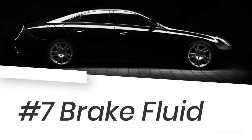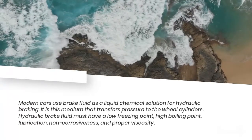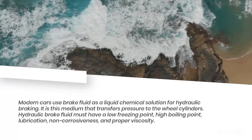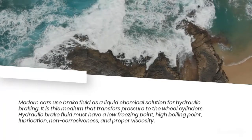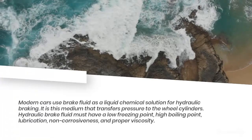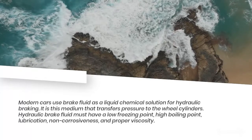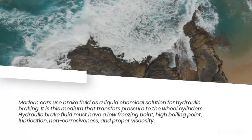Number 7. Brake fluid. Modern cars use brake fluid as a liquid chemical solution for hydraulic braking. It is this medium that transfers pressure to the wheel cylinders. Hydraulic brake fluid must have a low freezing point, high boiling point, lubrication, non-corrosiveness, and proper viscosity.